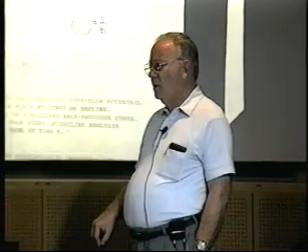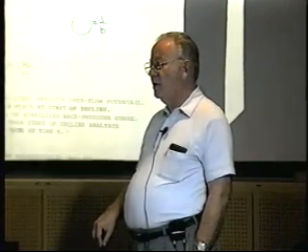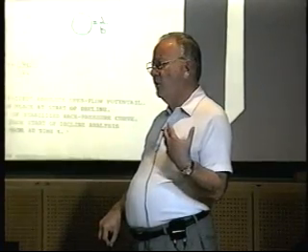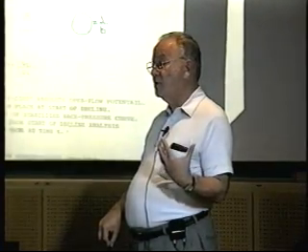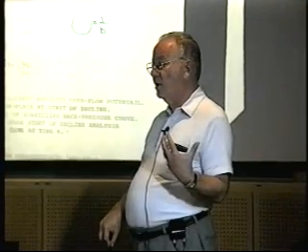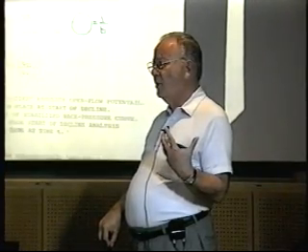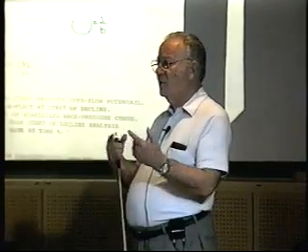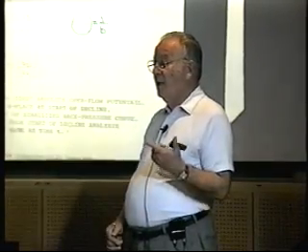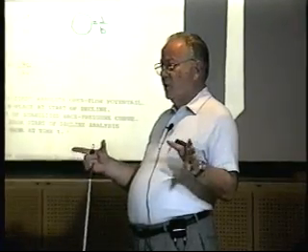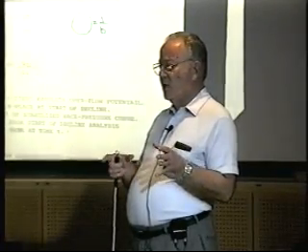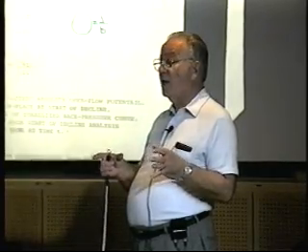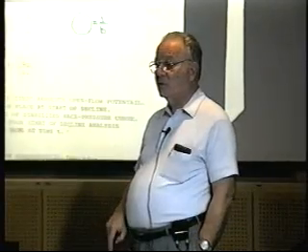And if you ever get into reservoir engineering, it's the same thing with regard to very low recovery factors. It's also trying to tell you the same thing, when you're relying on your volumetric as the original in place. Okay, you have an inverse problem here too. If your volumetrics are reasonably good and you're projecting a very low fraction recovery, it's implying that you may have a layered no crossflow reservoir system.